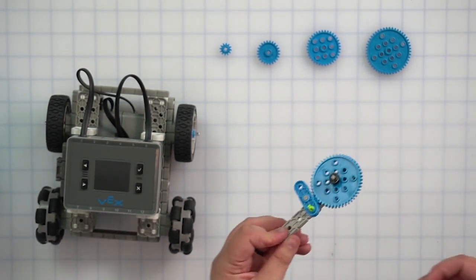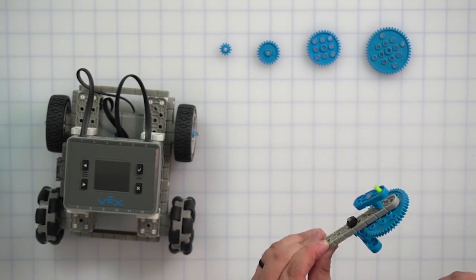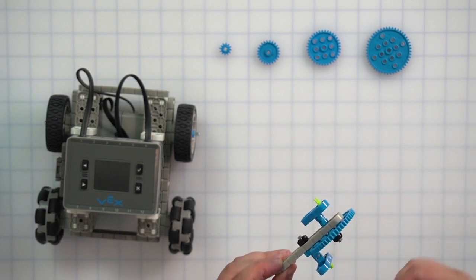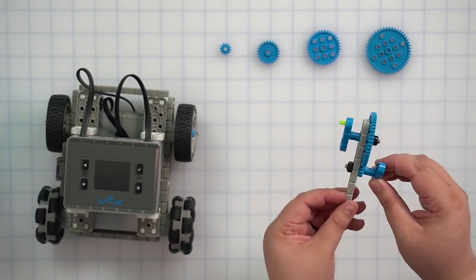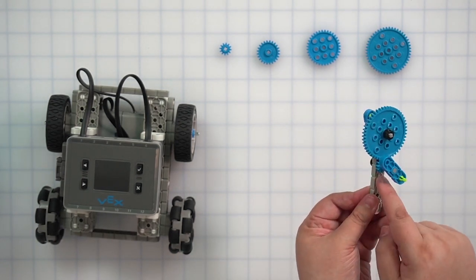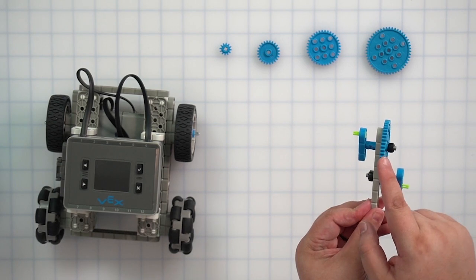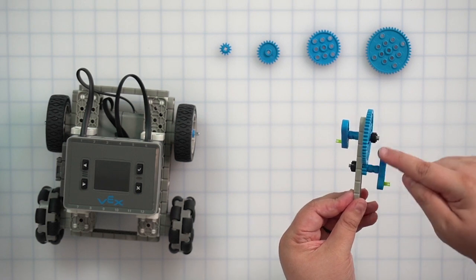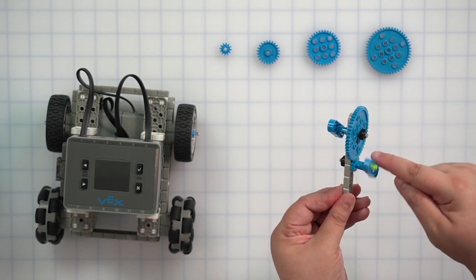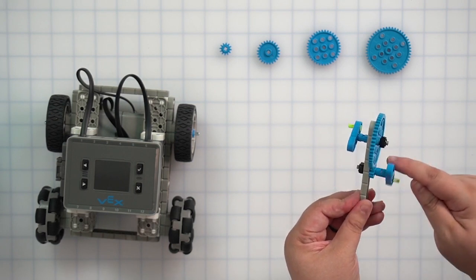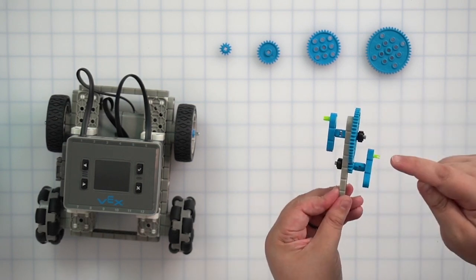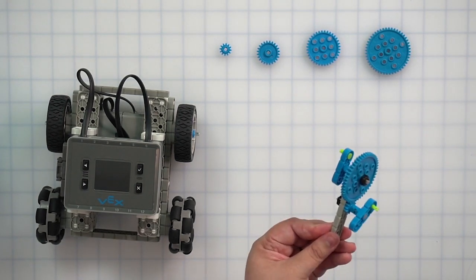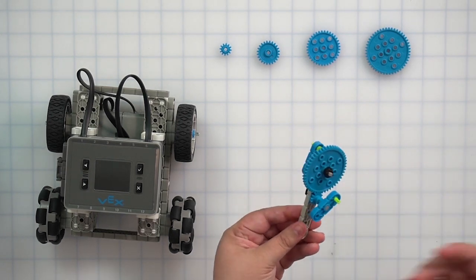In opposite, you have increased torque. Torque is the measure of force that can cause an object to rotate about an axis, also known as rotational force. So you'll see more of an output force here. If I spin the small gear, the 12-tooth, as my input, and watch the 48-tooth as my output, or driven gear, you can see I have to spin the 12-tooth gear 4 times before the 48-tooth gear makes it all the way around. So the speed is slower, but it also allows the output force to be increased, which is also known as an increase in torque.